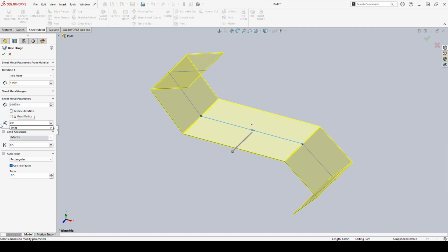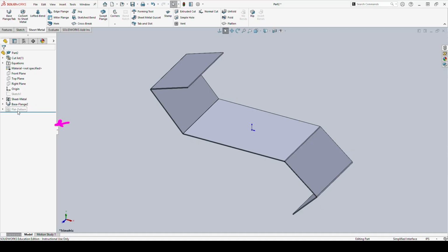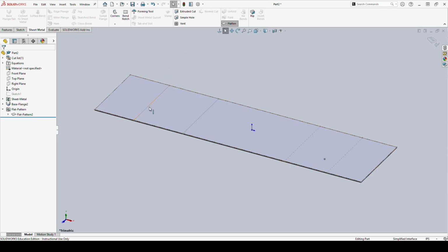And now I have an extra piece here that is going to do with the bend radius of all of my curves in my part. So currently I've got a very small bend radius. There's not a ton happening here. I switch it and you're seeing a bit bigger bend. I make it even more ridiculously large and we're seeing an even bigger bend. So you've got that giant bend happening there versus a smaller bend here. I have the opportunity to change that, and changing it in that first piece that creates everything should change the base values for my sheet metal overall.